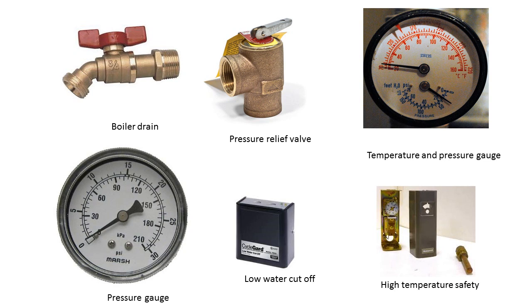On a forced hot water system, we have a high limit control called an aquastat. It ensures that the water temperature in the boiler does not exceed a certain temperature. When the water reaches the set temperature, the burner shuts off, until the water drops in temperature, then it'll restart.